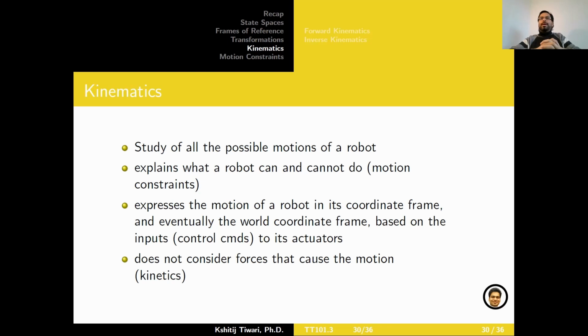And there are two branches of kinematics, which we're going to look into now. And remember that kinematics does not consider the forces that are required to cause the motion. So for example, if there is a block that I have placed here and I want it to be there and I use my finger to push it, that pushing is the force that made the motion happen. And I don't care about these forces that are causing the motion when I'm talking about kinematics. That falls under the category of kinetics, which is a completely different field of study. Okay, so kinematics does not really care about the causal forces.